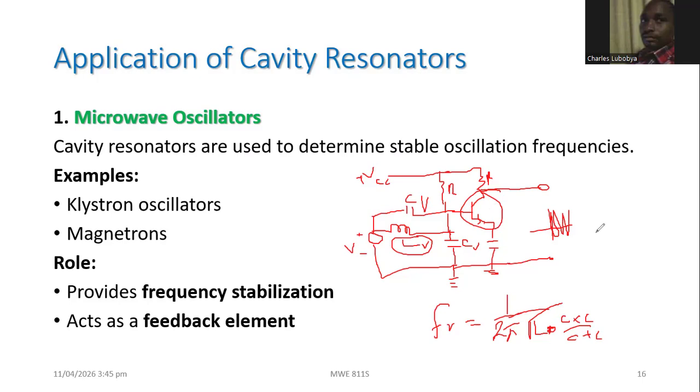And that's how you get the oscillations. And then this is now what you feed. For example, in a transmitter, this output here actually goes to your modulator circuit, and then it mixes with the audio signal, which then that audio signal is modulated in accordance with the frequency of this carrier.